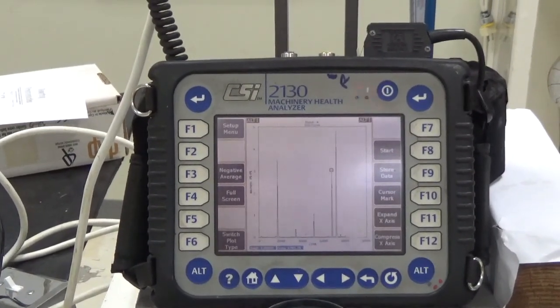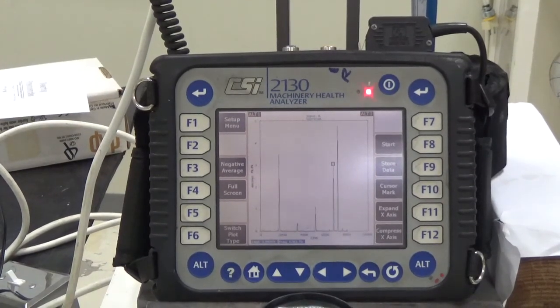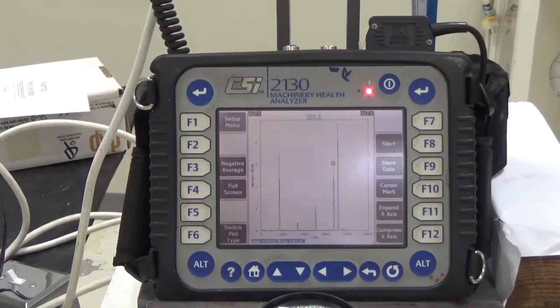Amplitude is the amount of vibration, and it tells you how much is the fault, or you can say what is the condition of that part. And the frequency is telling you what is the fault, which part is faulty, from where this frequency is coming. If this frequency is coming from the bearing, then the bearing is damaged. If it is coming from the gear, then the gear is damaged. If this frequency is equal to the RPM of the machine, it means that the machine is unbalanced. If you see two frequencies, one equal to RPM and the other double of RPM, it means that the machine is misaligned, or there is a misalignment.